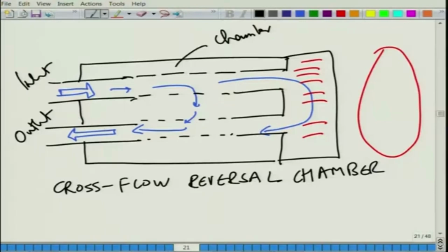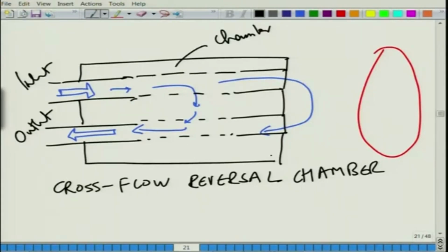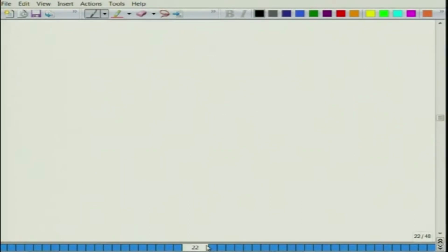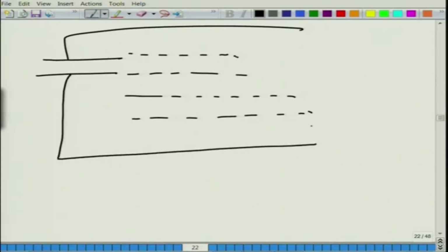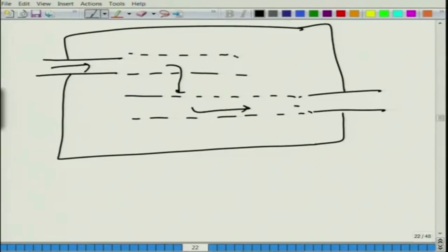This is just one very simple example. There are much more complicated examples of multiply connected mufflers. Then of course, talking about such configurations, there are many more that one can probably deal with. Another configuration that we have is your extended non-overlapping perforated element. So, this can be something like this. You have a pipe like this, and there are non-uniform sections like this, and you have perforates all across like this. So, the flow comes here, it has to go through this, and finally leaves. Okay.